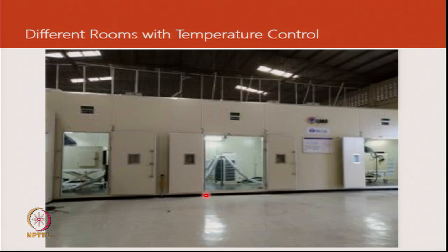When it comes to compliance to standards, then the method used is a balanced ambient calorimeter. So what is in the next picture, I can show you some examples of typical test rooms. Here this is a unit where there are different rooms with different temperatures, and you can see 3 rooms here. So if we were to even test a unit which had 2 indoors and 1 outdoor in a test room of this type, we could do that. We could have individual capacities of the 2 units, and then when we use the psychrometric method, we can also make use of the condenser side capacity.